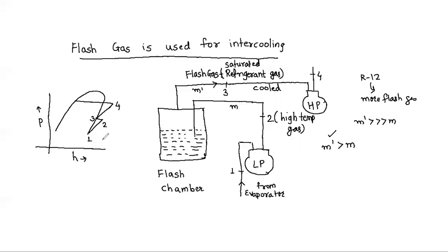We had a gain in terms of reduced enthalpy drop in the compressor. Whatever gain we get in terms of enthalpy difference is nullified because of the increase in the mass flow rate. So flash gas removal is always desirable, but flash intercooling, I'm not saying always, might increase the overall compressor work.